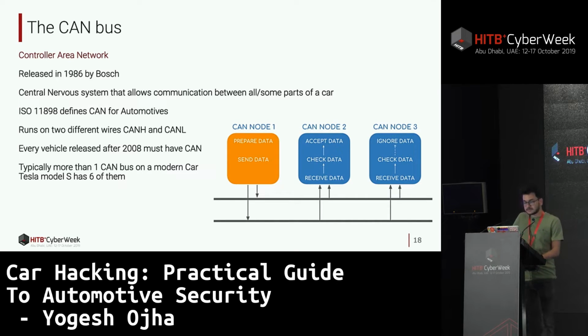So what happens is, when a bit is transmitted in a CAN bus, the signal will simultaneously broadcast one voltage higher and one voltage lower. So when the CAN bus is resting, the voltage that you see is 2.5 volts. But when you send, depending on what kind of data packet is sent, it's going to be either 1 volt higher or 1 volt lower. That's going to be either 3.5 or 1.5 volts.